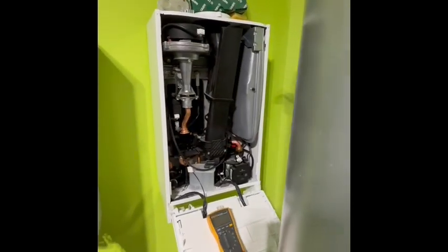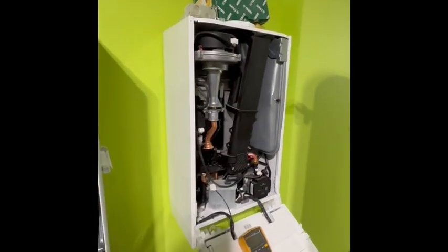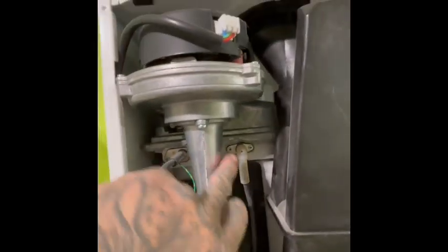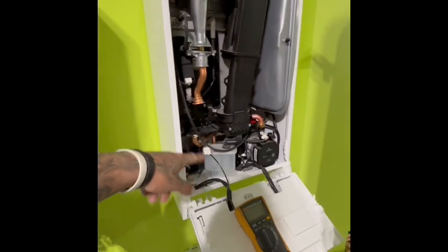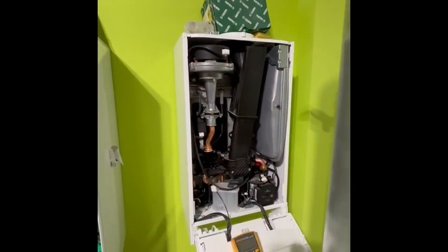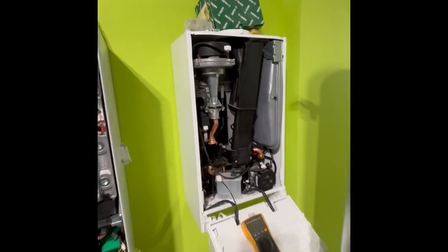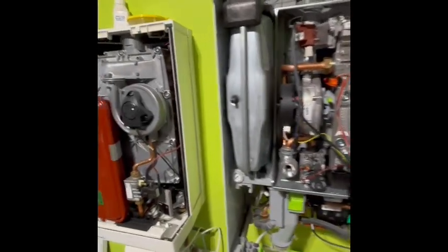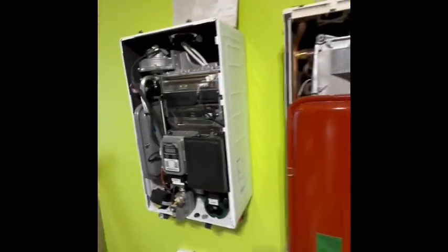and inspect everything. Another thing to note as well is if we've got a detection electrode. So on this Ideal boiler there, we've got a detection electrode. There's a little hole in the back of it. That's a test point to put your test probe from a multimeter down to another point and take a reading to make sure that detection electrode is giving out the correct reading when it's sensing the flame. Again, those readings can be found in the manufacturer instructions. If you can't find them in there, phone the manufacturers and let them walk you through how you test through the ignition sequence.